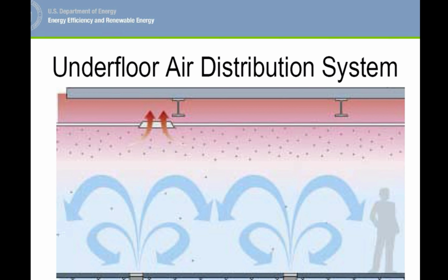As we talked about in class, there are a couple of different ways to distribute air. We talked about vents in the ceiling or vents on the floor, and how warm air will typically rise and occupy the space closer to the top of the ceiling, versus colder air that will usually sink towards the bottom. You'll generally have a couple of degrees differential between the floor air temperature and the ceiling air temperature.